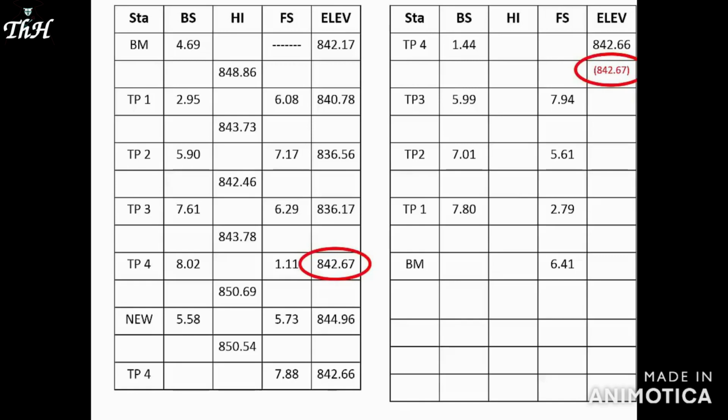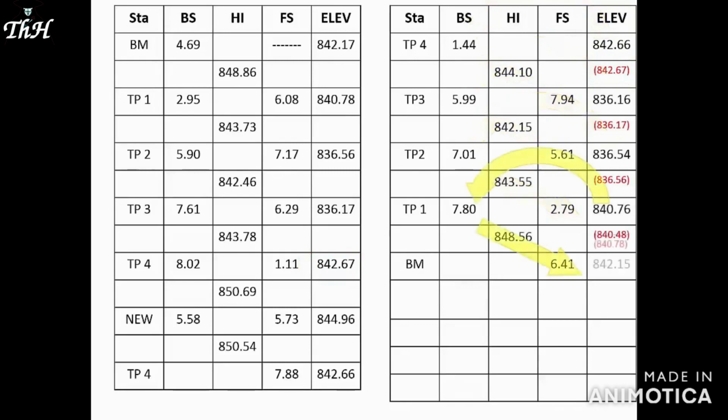This shows us then that we have small errors accumulating in our readings. This is a natural consequence of things like rounding our rod readings to the 100th of a foot. This type of check helps us find rod reading errors and math errors. So be sure to compare the elevations from your forward and reverse runs.